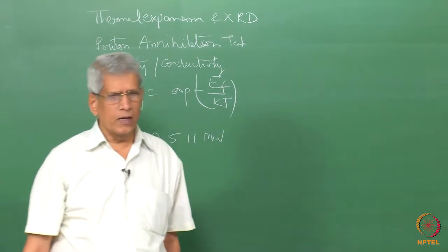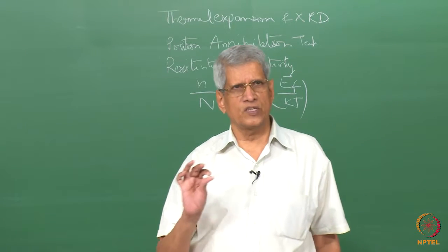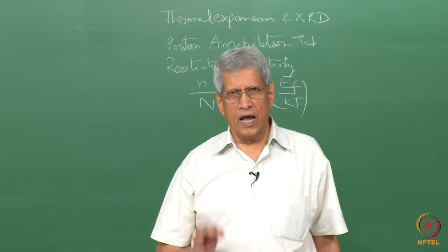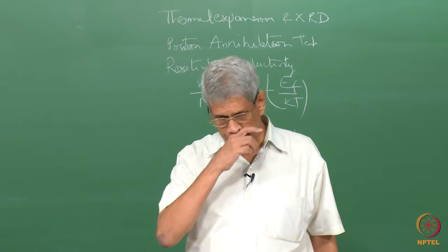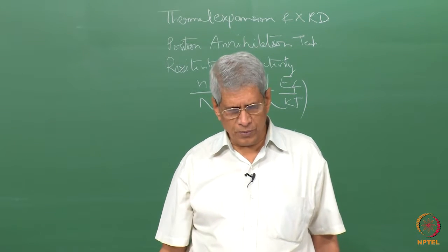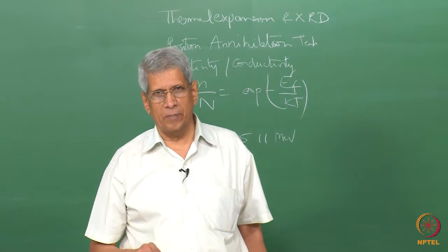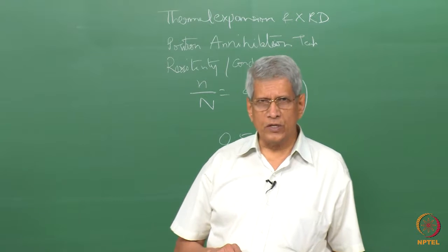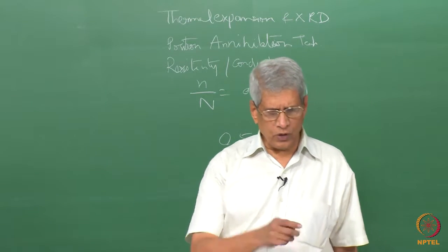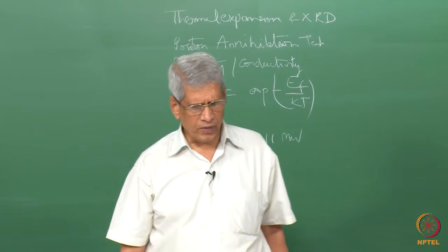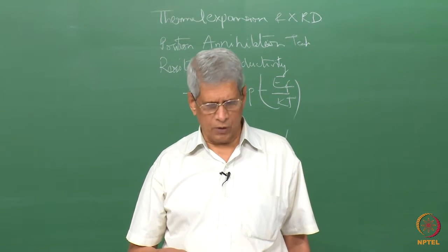Let us talk about some of the experimental techniques which are used, so that one is aware of how this technique could be used. This technique gives an absolute measure of the vacancy concentration which we can detect. What are the sources of isotopes? One is sodium-22, another is copper-64, and cobalt-58. Out of these, sodium is the one which has a gamma with the smallest energy coming out of the sample surface.